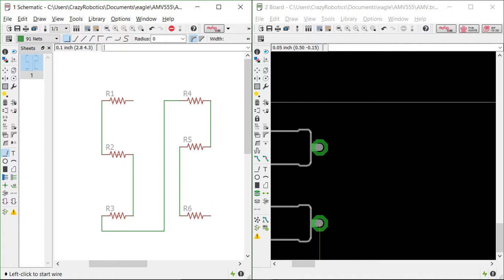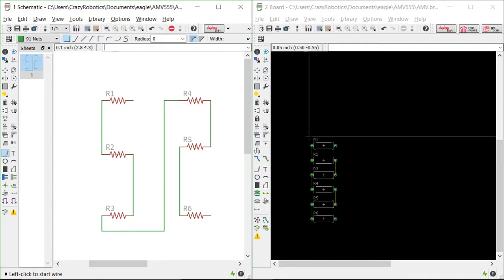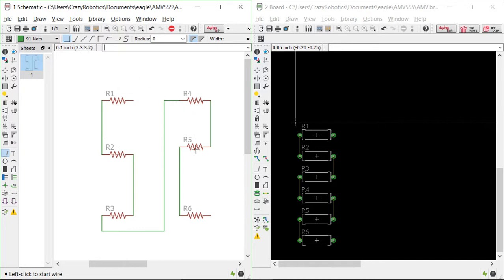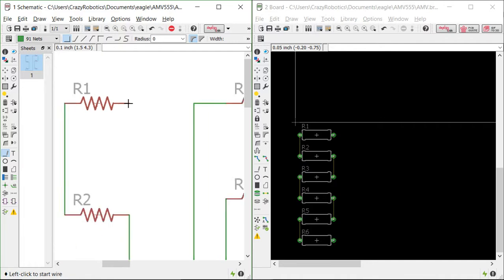So it's not a good method to directly use the lead or the terminal of a resistor itself as a port which can be utilized externally. So it's important that whenever you generate a schematic file, make sure that you are providing proper output terminals for each and every connection other than the original components' terminals.